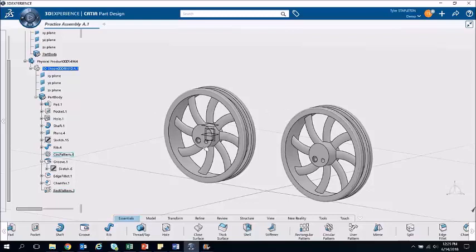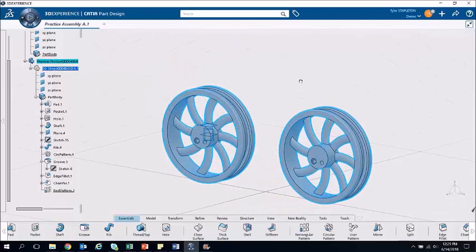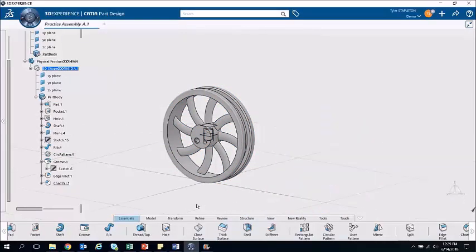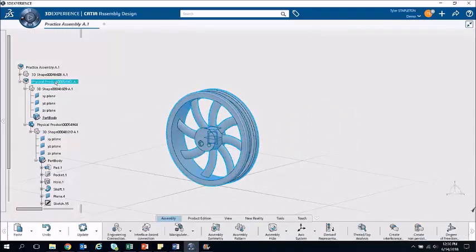One thing to keep in mind, however, if you're going to duplicate an entire part in this way, notice when I duplicated that, it's actually considering this whole object as part of the geometry that's defining this one part. So it's actually still thinking of both of these in our tree as one part. Now if you want to duplicate an entire part, rather than creating a rectangular pattern like this where they would be disconnected, I can actually come back to my original assembly, or the assembly containing this part.